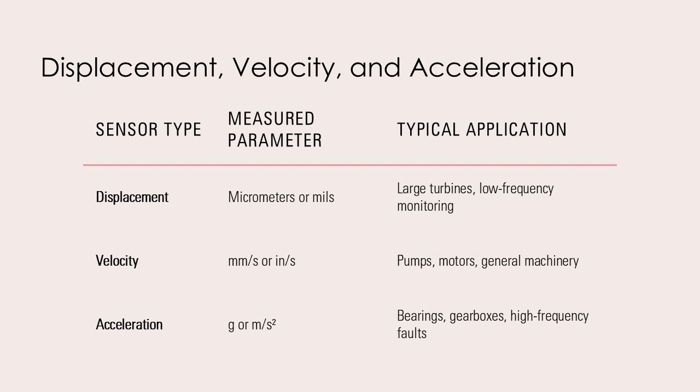Accelerometers measure acceleration and are suitable for high-frequency vibration analysis, such as detecting bearing faults. Understanding these units and their applications is crucial for selecting the right sensor for specific machinery and fault detection scenarios.